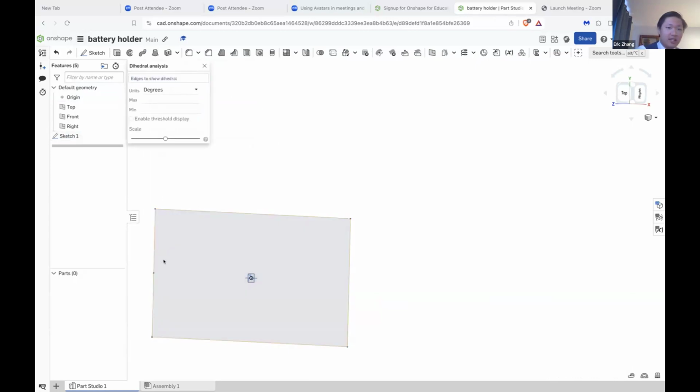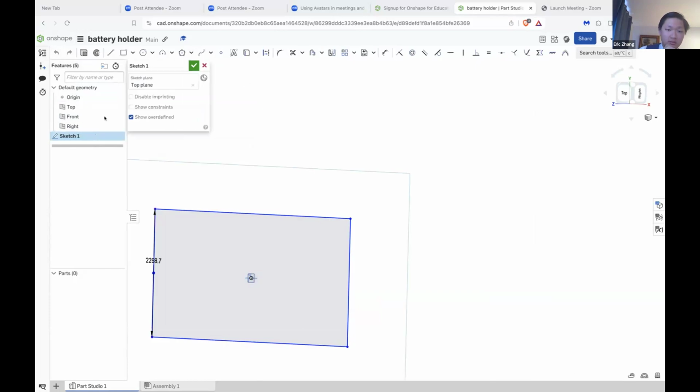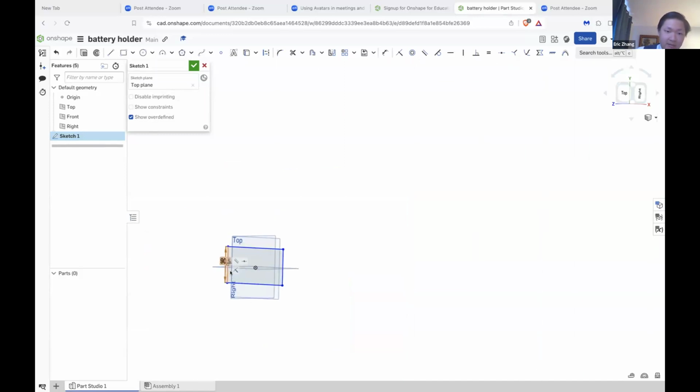So now double click on the sketch again. On the top, and in the right corner, right bar, now double click on the sketch. No, below. Yep, double click that. Great. And now you can go to the number. No, below. You see the number that shows how much the side is. Yep. Now change that to 90.4, not inches, because you see in the right side there's millimeters. Yep. Now press enter, and it'll be a much more normal size.